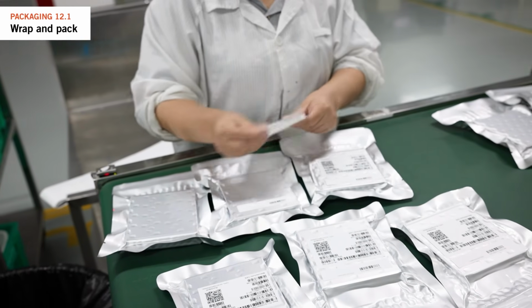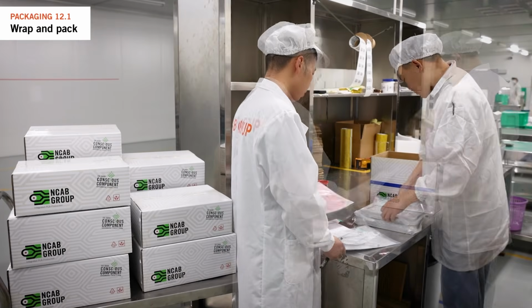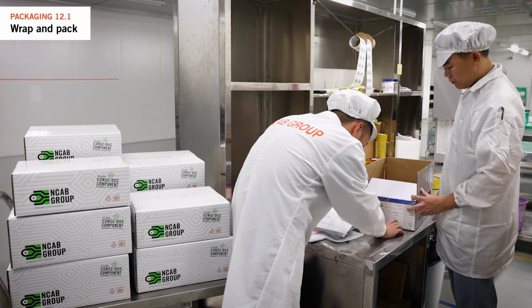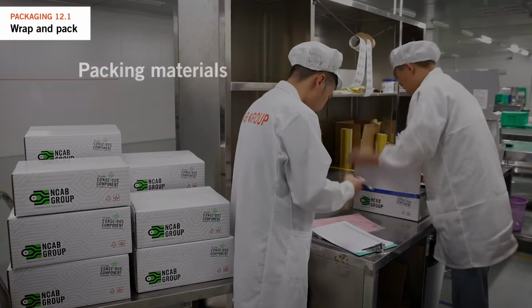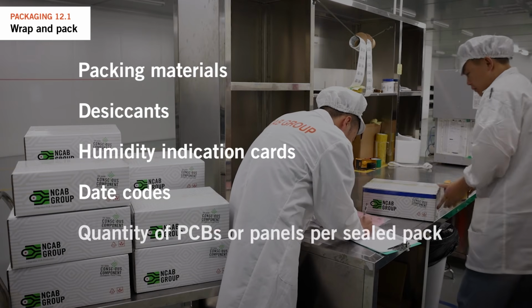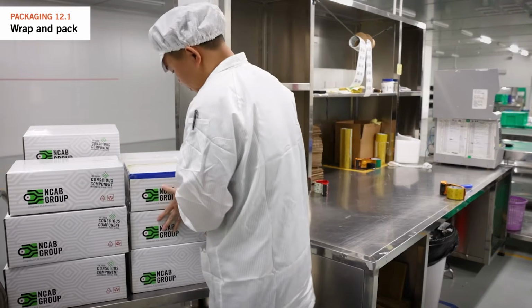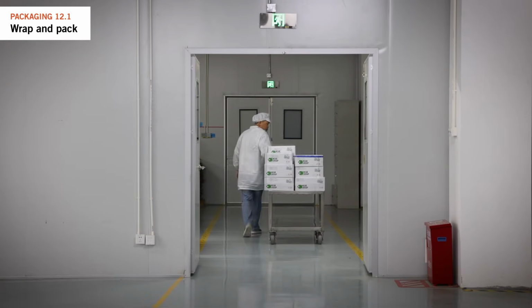A label with identification and traceability data is added to the sealed package, and packed into NCAB cardboard boxes. Upon customer request, a humidity indication card can be included inside the sealed package. Packing materials, desiccants, humidity indication card, date codes, and the quantity of PCBs or panels per sealed pack must comply with NCAB packaging and label instructions. Both inner and outer packages should have NCAB labels.